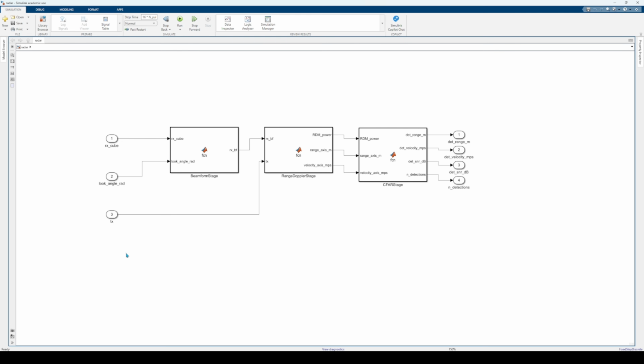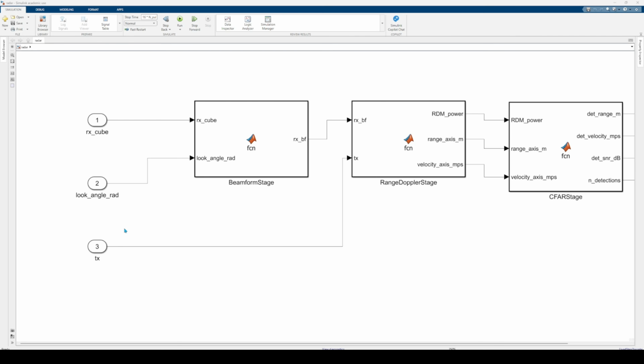Okay, now cutting to the second independent model, a complete pulsed radar signal processor: 3 MATLAB function blocks in series, MVDR beamforming, Range-Doppler processing, CFAR detection. All authored so that the generated C is pure ANSI with no Phased Array Toolbox dependency. The input is a raw IQ cube, 2500 range samples, 8 antenna elements, and 16 pulses per coherent processing interval.